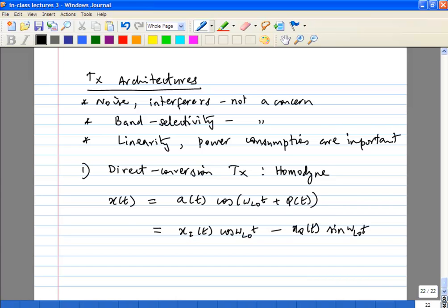However, people do talk of what is called a complex signal because these are the two things which you produce from the baseband. So you produce an in-phase component and a quadrature component, if you think of it in terms of Cartesian coordinates. So what you produce from the baseband are in-phase and quadrature, or amplitude and phase, depending on if you have a polar transmitter. There are classes of transmitters called polar transmitters where you work with the amplitude and the phase, okay, that we won't discuss in this course. But the typical standard transmitter would use I and Q, okay. So xi of t and xq of t are the signals you are interested in, okay.